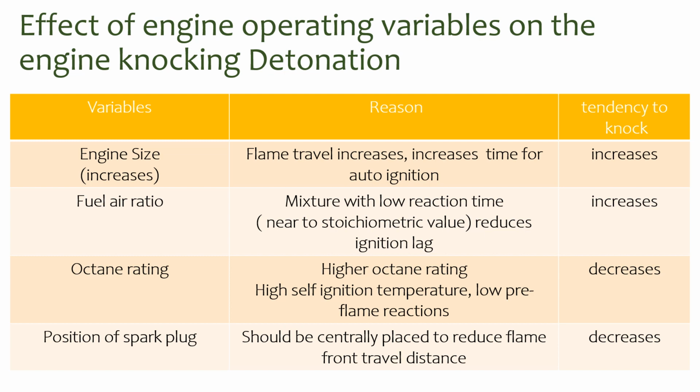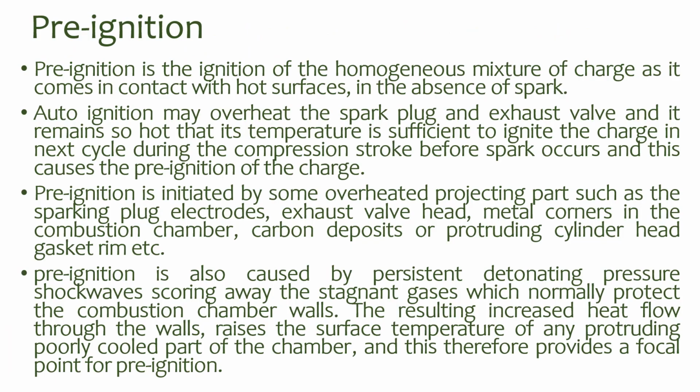That's why the octane rating is based on the knocking tendency. If we keep the spark plug centrally placed, it will reduce the flame front travel distance, so that will also decrease the tendency to knock.